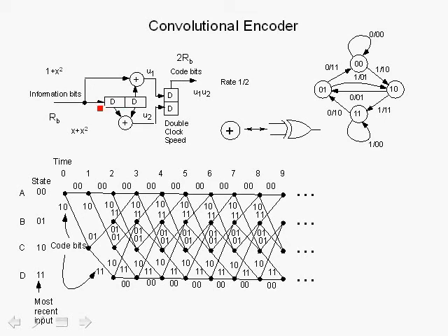So the 1 would be shifted in, and the 0 would be shifted into the next shift register bit position, and we get a 1, 0. In the case of a 1, 0, if we input another 1, the 1 would get shifted, and the 1 would be entered into the first shift register element, and we go to state 1, 1.